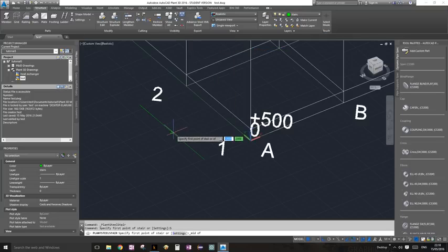So I can only select midpoint, not endpoints, nothing else. With every object, I can only select midpoint. So on my outside line, I'm going to choose the midpoint of that line. And then I'm going to choose the midpoint of the second bit of grid there. As you can see, click on that and press escape to get out.